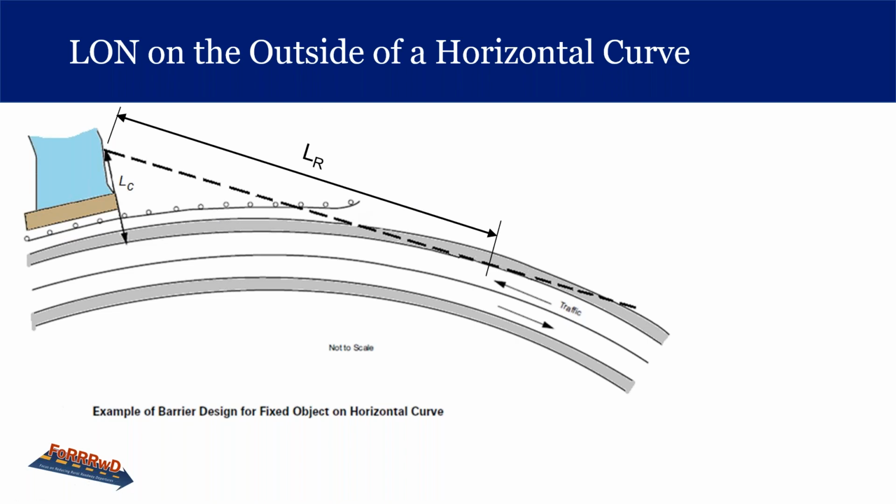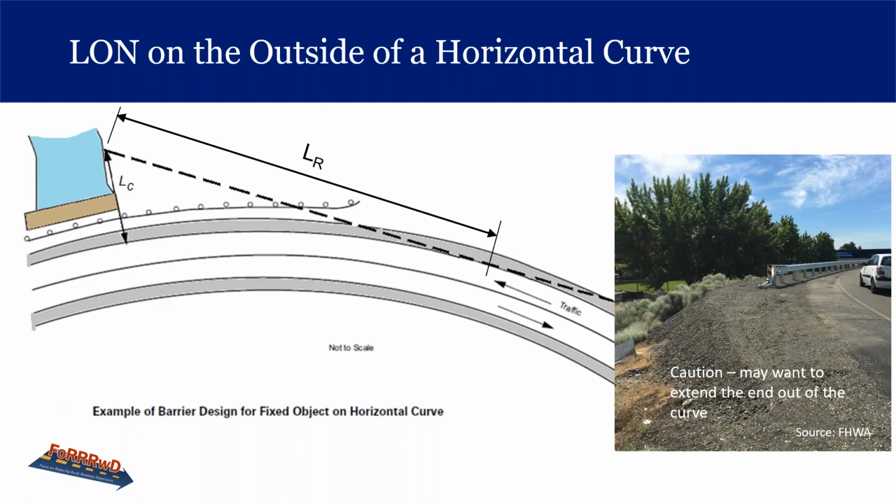But we have to use caution since guardrail terminals pose a greater risk than a standard run. And since many roadway departures happen on curves, it may be more desirable to extend the guardrail around the curve in some cases. So you can see here.